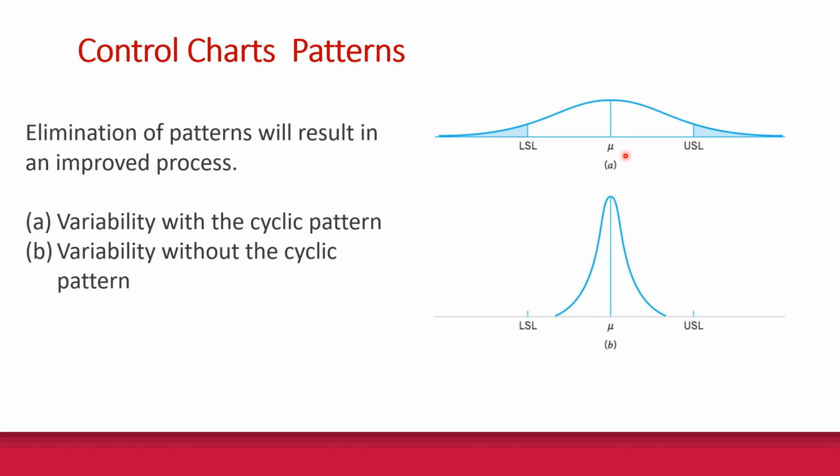So if you were manufacturing product, which of these would you prefer to have, A or B here? This one's got some problems, right? You're manufacturing products that fall outside of the spec line, so obviously that's a problem. Theoretically, you'd want it to be as centered as possible, and the variance to be very, very tight. You want some room for error, so if the process shifts just a little bit, you'll still be within control. So ideally, you want this very narrow.